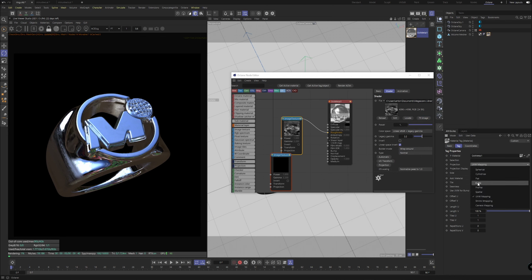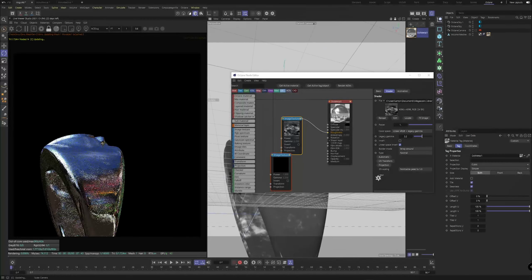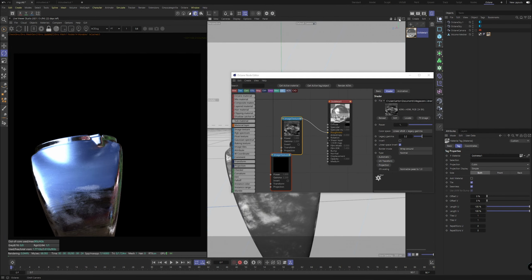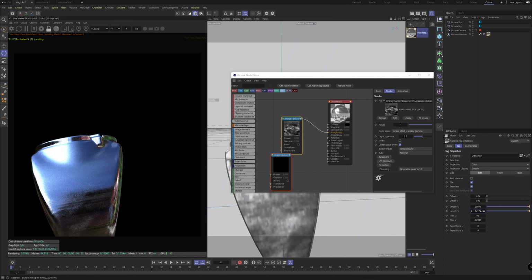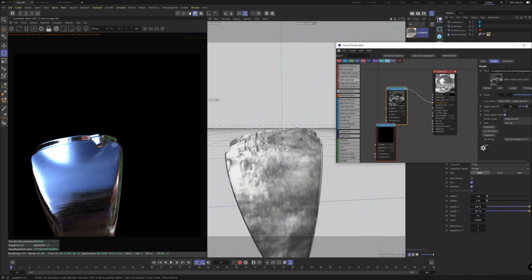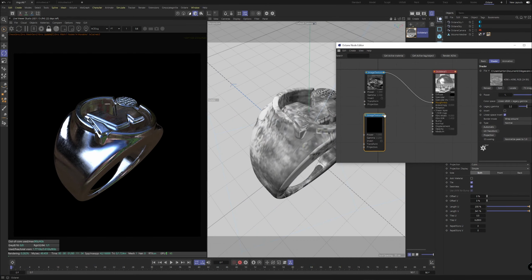If we set this to cubic and seamless, because bear in mind this isn't UV'd at the moment, that should give us a bit more of a shot of getting some of those scratches there, you see. We can also just tweak the UVs here. So if we want to make this a little bigger, we can set this to 200. If you increase that, you can see we're getting a pretty good reflection of what we want. We're getting some speckles on it as well, which looks quite cool. So that's just our mask layer. If we wanted to replace that with our roughness, we could.